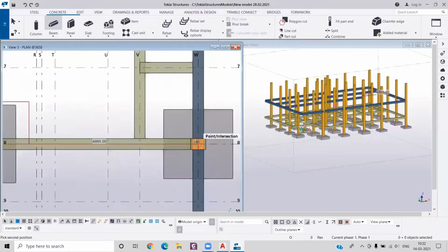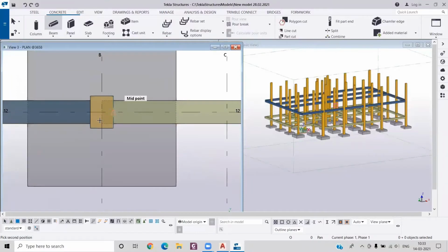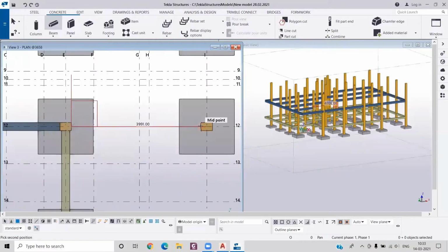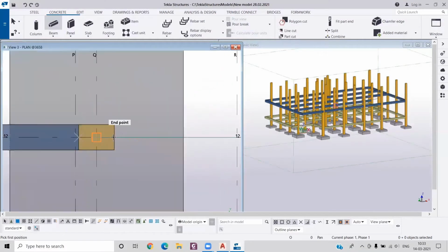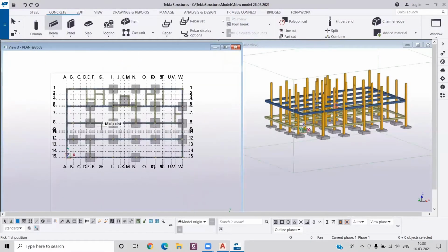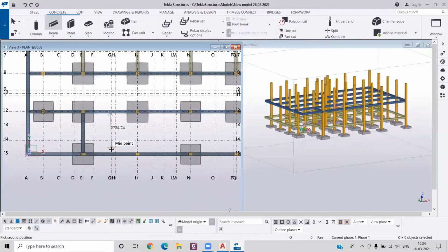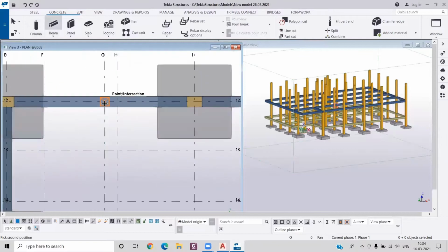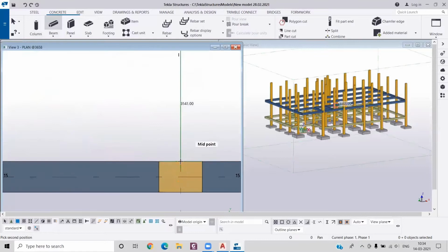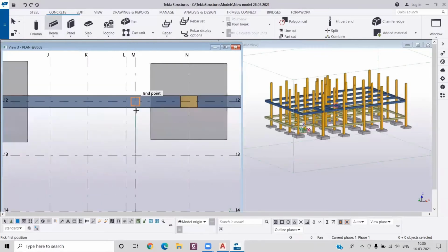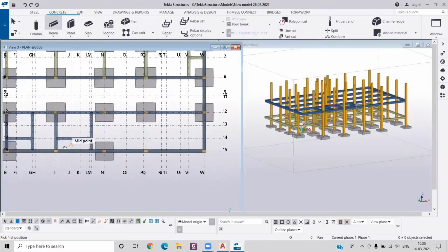And there is one more thing that you can notice over here. In this I am not defining the size of each and every beam over here. Why so? Because I can always change the size whenever I want. So first of all, I would like to place the beams, then I will change the sizes or the properties of the beams according to the requirement of the structural drawing. But at first I need to position all my beams accurately because all the beams that I have over here have 250 mm in one direction.